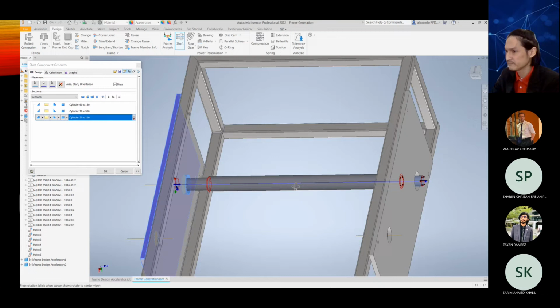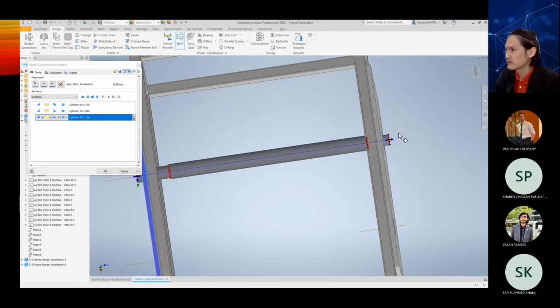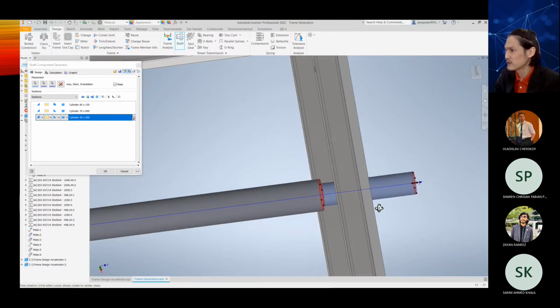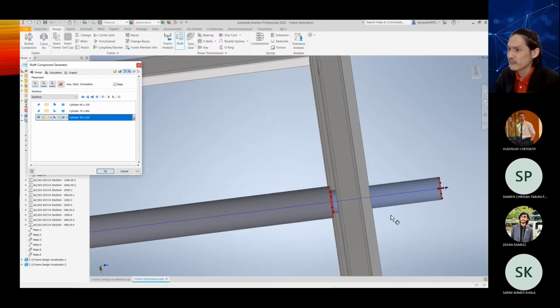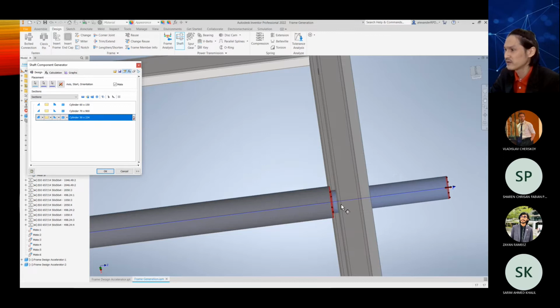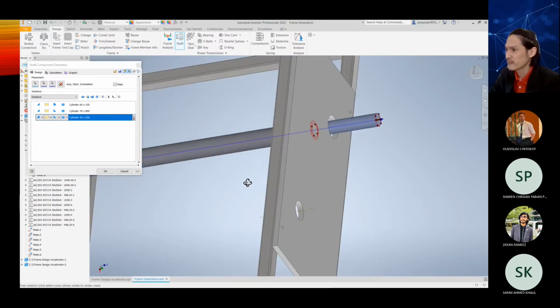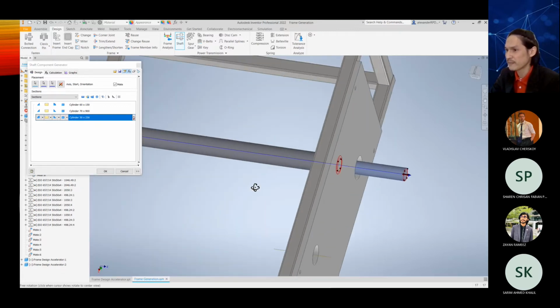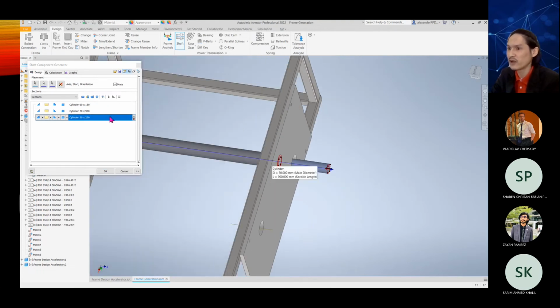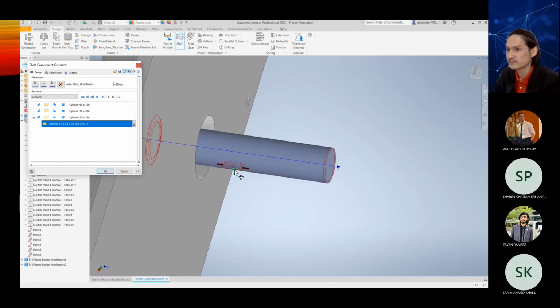If everything okay, then you can, let's say I want to enlarge it again, make it longer. So make it a number, maybe just a nice number. If everything okay, then you can click. If let's say you find that you still need some other things, for example, this one is very long, I want to create a keyway. Then you can add a keyway over there.